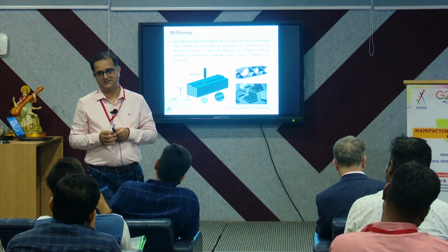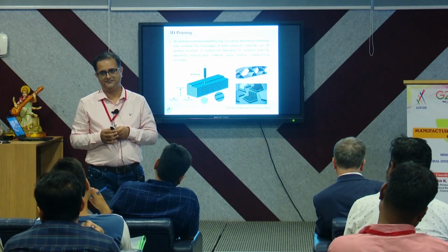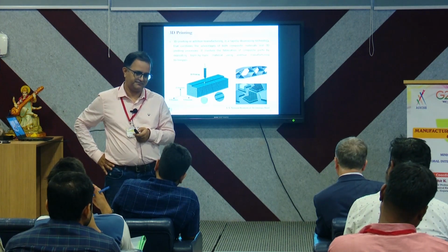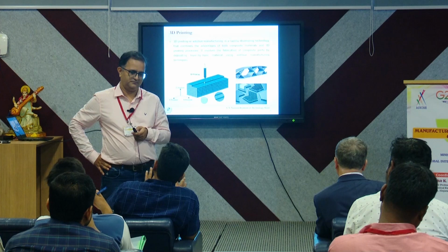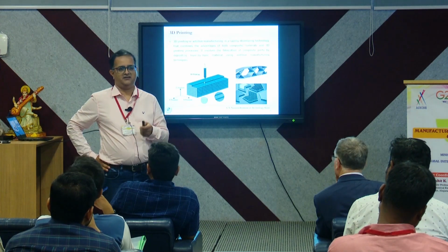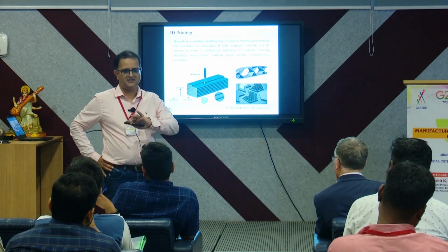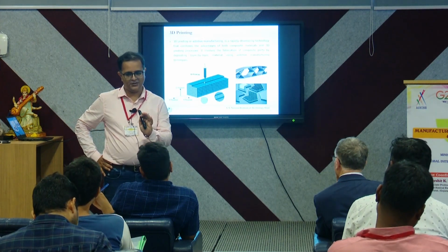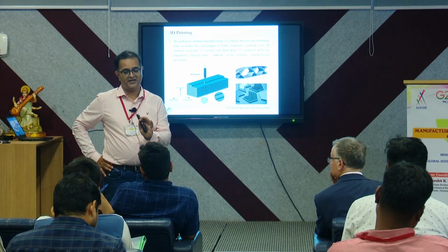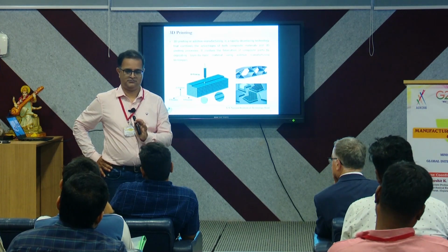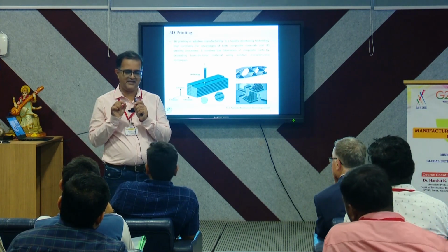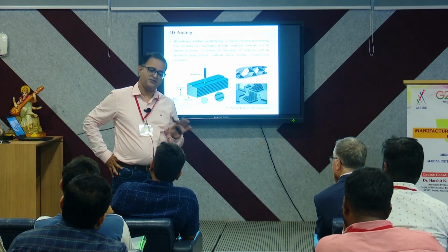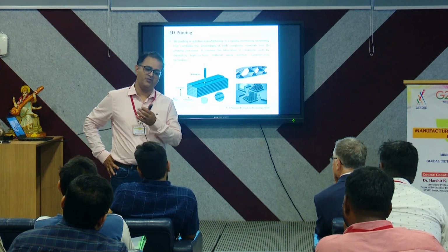Yes, with this process they are being made. One more thing, that we are pulling it. Rather than pulling, why don't we push it? The same thing. Once the shape is a complex shape, then when you are pushing it and the resin is passing through it, it does not have a way to always push the air out. If air is trapped somewhere, it remains there. Whereas when you are creating vacuum, it means there is no air inside. You have already removed air.